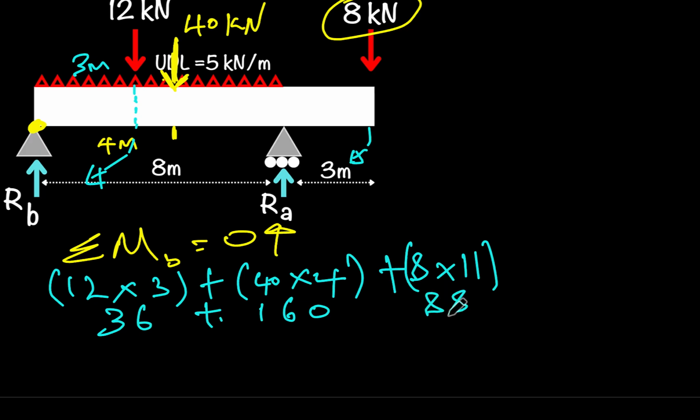So now RA is going to go counterclockwise. So the RA force is acting like that, as you can see from the arrow, so it's going to go counterclockwise. So I'm going to write this as negative, because counterclockwise indicates a negative turn. So we're going to have minus RA multiplied by 8, and all of that equals 0.